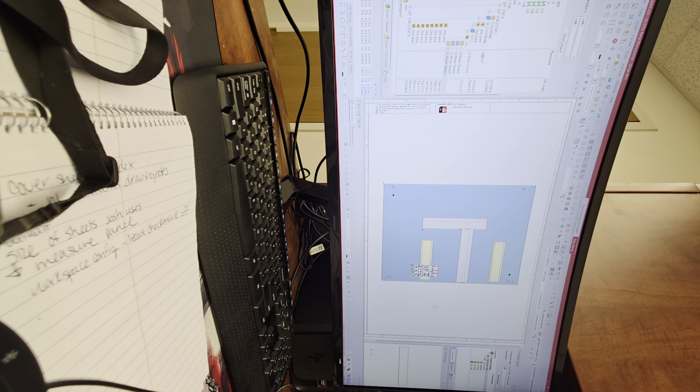Okay. So what I would do is, you would definitely need a duct above your rail and one duct below your bottom rail, because you have some wires that are wrapping themselves around. All right, so we need that one, and one all the way on the top. The top one is going to be tight. So for the top one, I'll show you a little trick that I remember doing from a UK customer here.